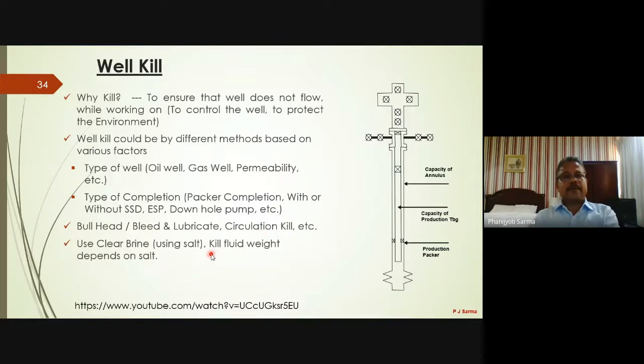And always in a workover, it's not like drilling, we always use clean brine, because some of this brine will be lost in the formation. So we need to have a clear brine so that we do not damage the formation in the process of killing.